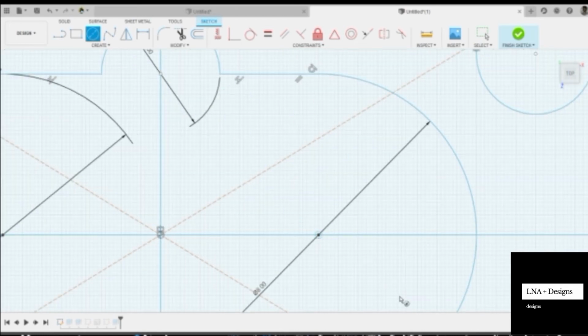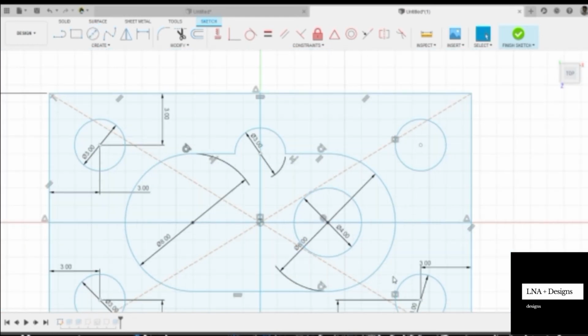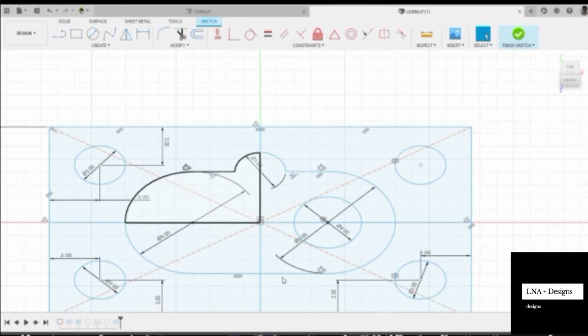Again, see, here we want it from the midpoint of the circle, and this is going to be 5 mm dia, not 5 mm. Sorry, it's going to be 4 mm dia. And what I said is it should have the depth of 4.5.